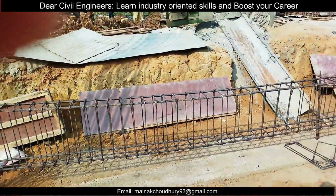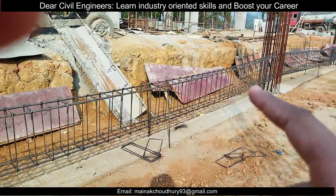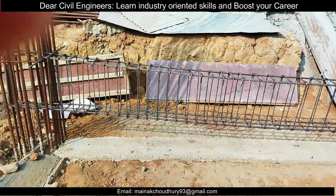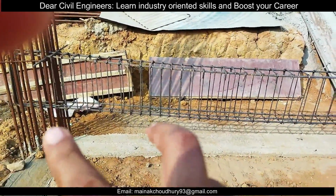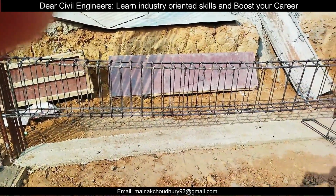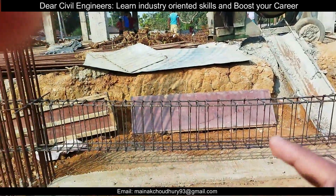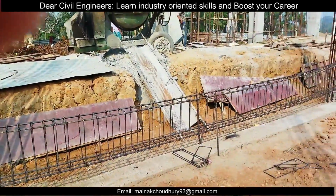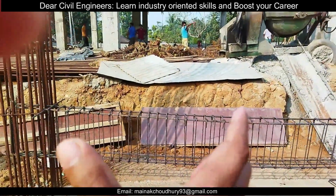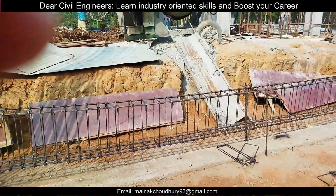So if from here to here is L, that is one span between two columns, then the lapping for the bottom can be done at a distance leaving L/4 from here. Then you can do the lapping for the bottom. And for the top, if you divide the span into L/3, there are 3 parts. Let's suppose the first part is up to this, the middle part is up to this, and the last part is up to this. In the middle part, we can do the lapping for the top rebars.